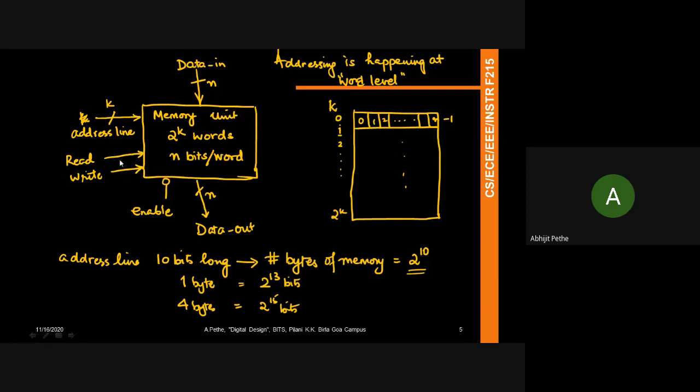So the total time this write has to be high really depends on what is the worst case time required for this memory to write from data into the memory, right? So again, what I'm giving you is a very, very simplistic view of memory. In reality, a lot of tests need to be done for you to figure out what is the worst case write time. Like what is the pulse width I need to ensure write has, so that any time I give a data input word, it is written reliably into the memory, right? So you need to understand what the worst case is, and you need to plan for that whenever you want to write or read into the memory.